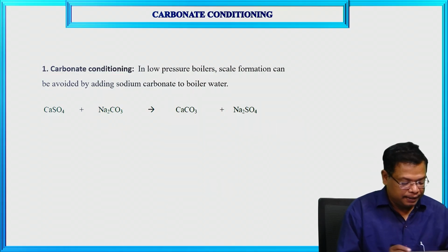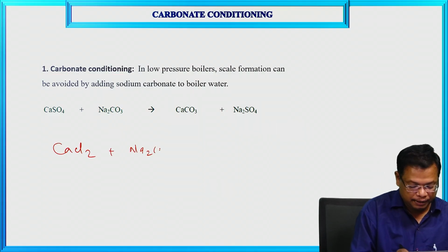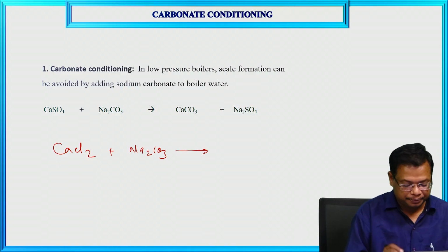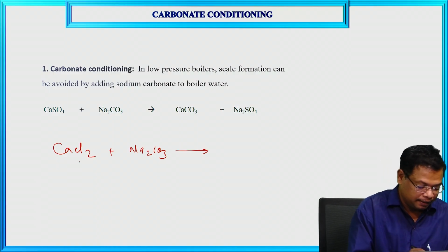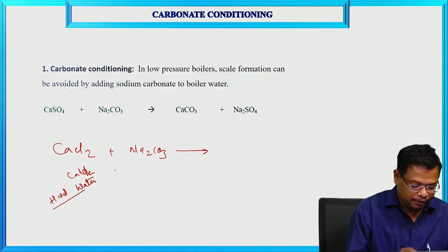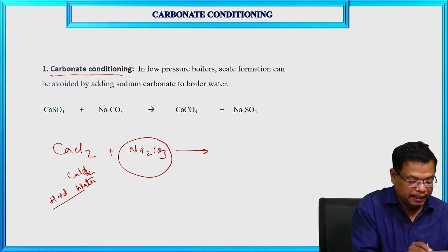Likewise, if CaCl2 plus Na2CO3, if you treat the hardness causing salt CaCl2 in hard water, you remove this salt by adding Na2CO3, carbonate conditioning.